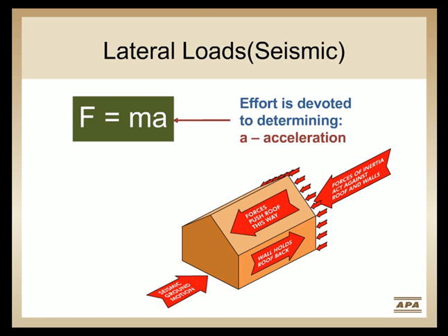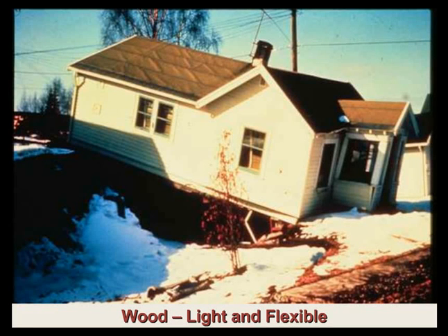A benefit of wood frame construction is that it does have a high strength to weight ratio, so that's very useful in being able to efficiently design these buildings to resist the force. Yet in California in particular, we have a trend for using a lot of concrete tile on our roof, which will again increase the mass of the building materials and impact our design.